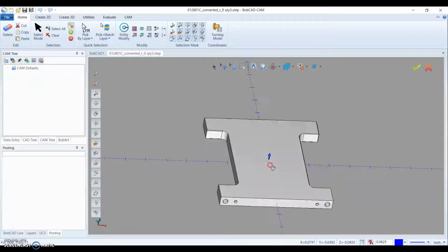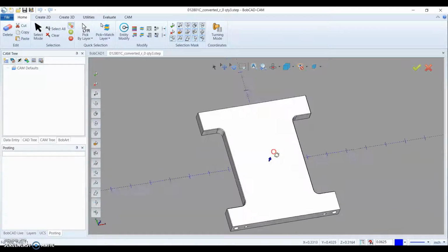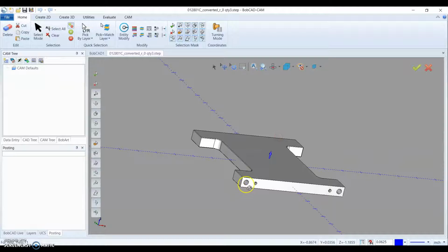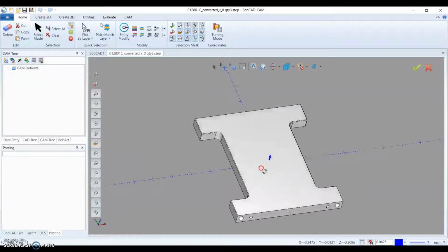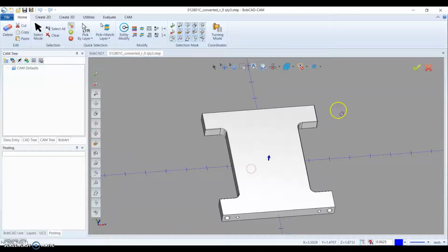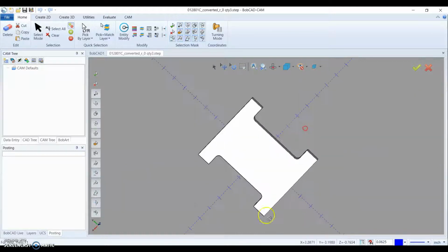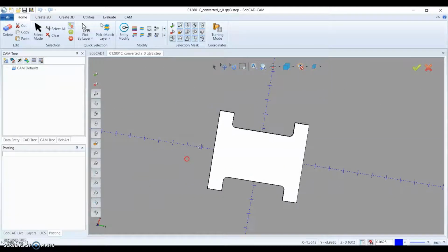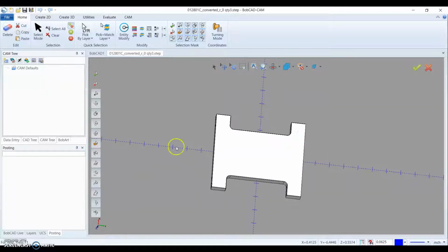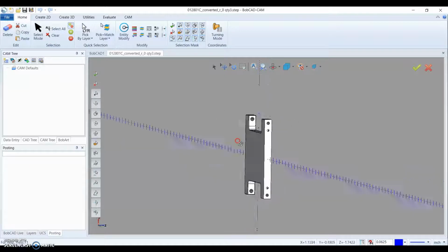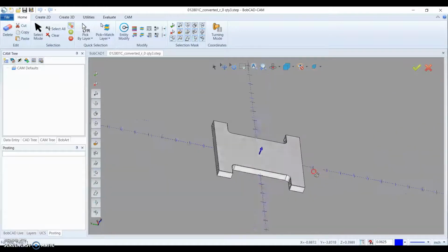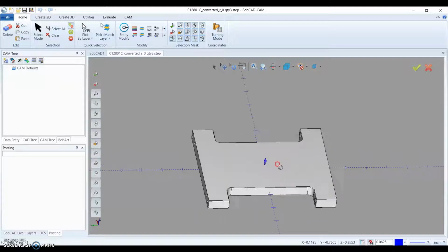So just looking at this part, it looks like it's a good candidate to cube, meaning I'm just going to leave more material below the bottom of the part. I'm going to stick it in the vise and then face mill it and mill the periphery and then flip it back over, hold it in a vise like so, and then flip and deck the other side to size and be done with it. So if this is a 1/2 inch part, I'm probably going to make it out of that 5/8 material so that I can clean up all faces.